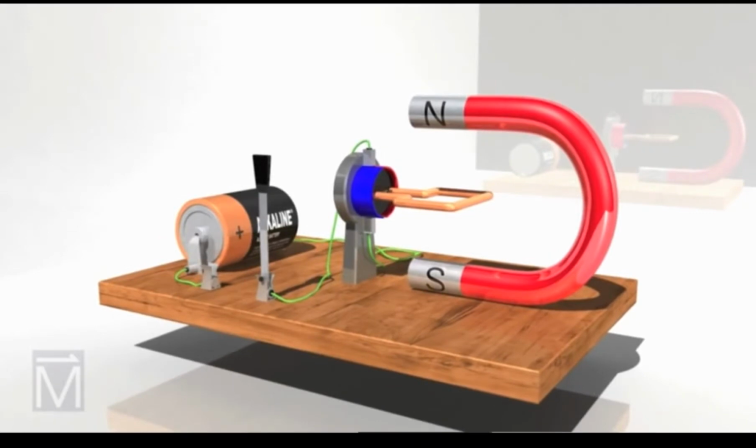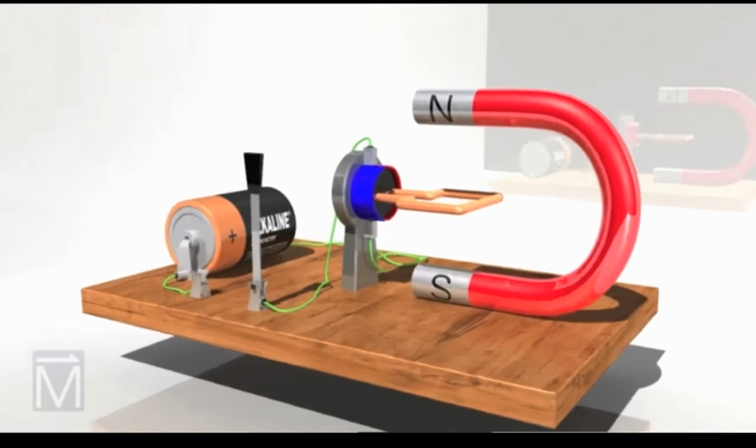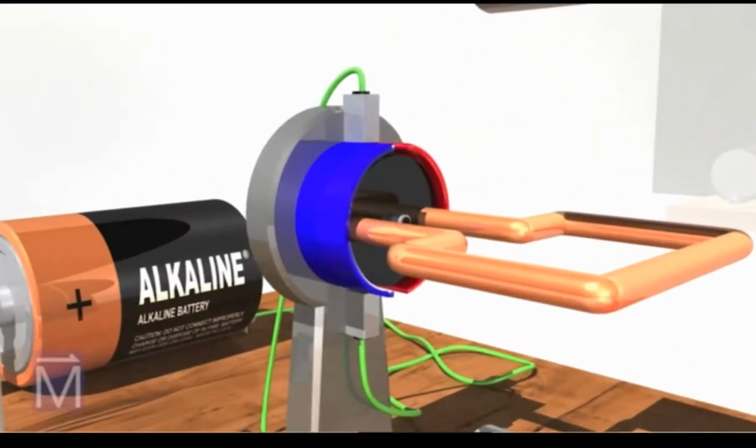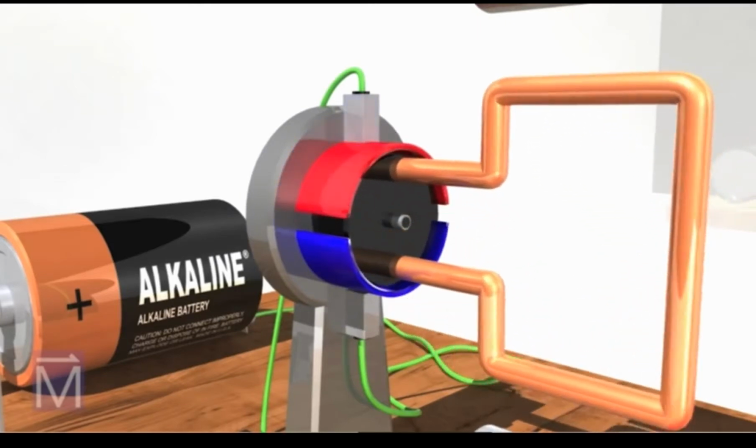endless types of work. The current that runs into the armature passes first through one of these graphite brushes, then through one of the two semicircles that make up what is called a commutator, which is a rotary electrical switch made of copper and featuring two gaps. The cleverly designed commutator is key to making the DC motor work.